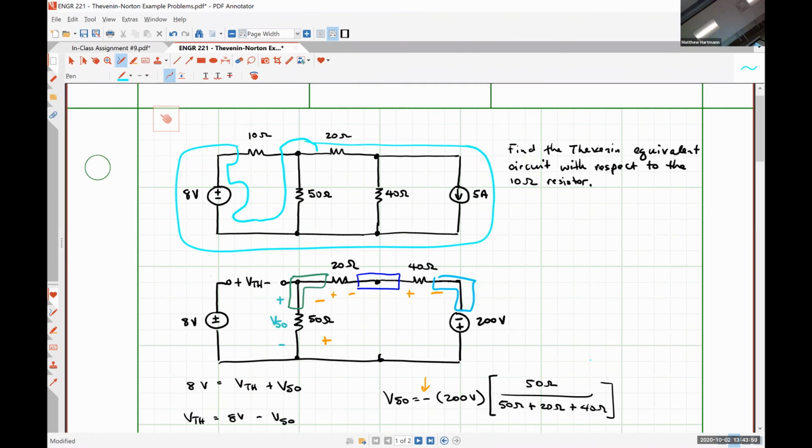I only need to look at the open circuit voltage and/or the short circuit current and/or the Thevenin resistance to be able to know exactly how much power that particular subsystem is going to be able to dissipate for a particular load. So it's a shorthand method that we use in practical electrical engineering to save ourselves a lot of trouble of analyzing big ugly circuits when we can simply hook up a voltmeter and a multimeter and figure out how it's going to behave from two figures of interest.